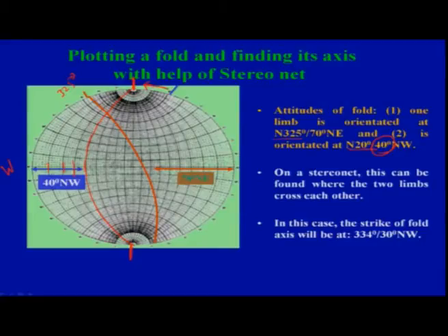So again you are getting another one, that is the blue plane, and you will get the information here. Okay. So again you move back in the same fashion, bring your north, which was initially marked. When you start this, it is better to mark the north, south and east, west. That will help you in bringing back your tracing, and this has been done on the tracing sheet. So you will put the stereo net, and you can do this on the tracing sheet.